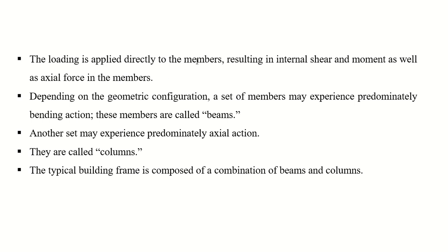If you remember, in the truss structures, the loading was applied only at the joints. However, in the frames, the loading is directly applied to the beam or column, resulting in internal shear and moment as well as axial forces in the members. So, in the frame members, there is an axial force, there is a shear force, and there is a bending moment.